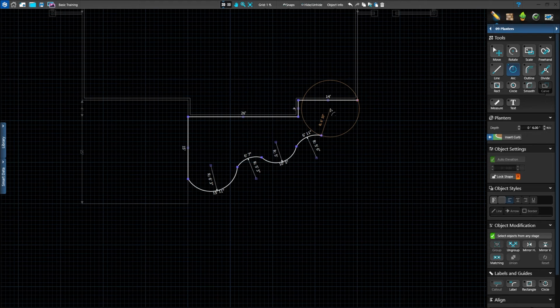With the arc set in place, trace the final arc and click to complete the shape. To adjust the arcs, activate the Move tool and drag the points between the arcs to create smoother transitions. The more we work with the Arc tool, the easier it will become. Let's use another method to create our freeform planter.